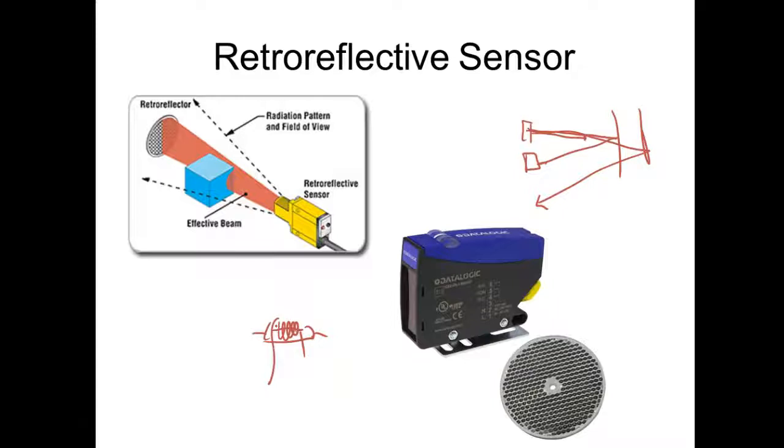A solid state sensor, or one that has a transistor output, you can only run those things on DC. The signal is a DC signal. A relay output is whatever you put on there. So the Siemens PLCs have DC outputs.